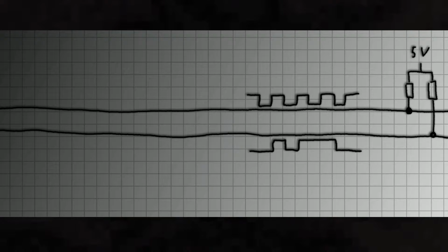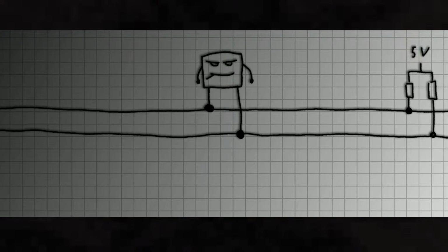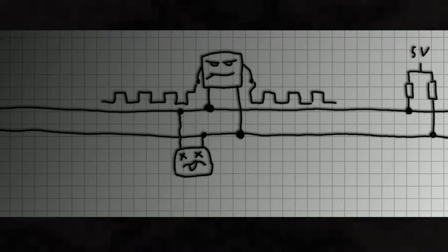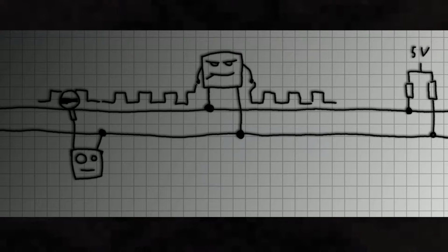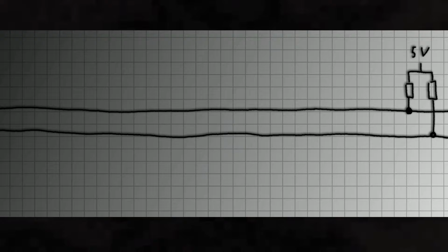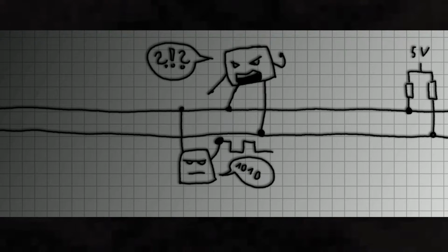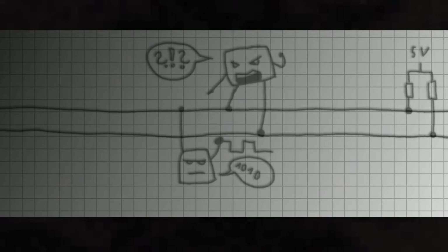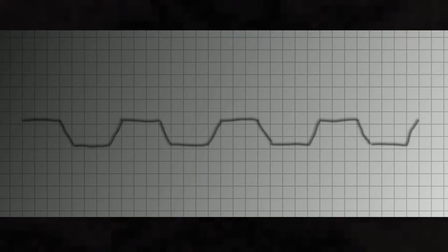Each node is assigned one of two roles, master or slave. On a bus, there is one master and multiple slaves. The master has exclusive control over the clock line. The slaves may read the clock signal, but they must not change its value. Write access to the data line is switched between master and slaves depending on whose turn it is. When nothing is going on, the only output is the clock signal. In fact, even that might be disabled because a clock signal is only needed during active communication.